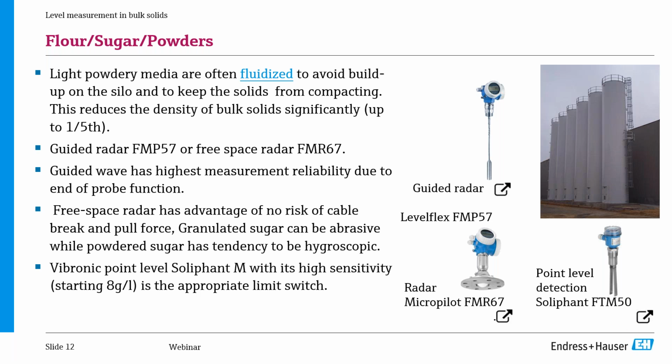Free space radars, depending on the process conditions inside the silo, can suffer what we call echo loss, especially if you have a very dusty cloud inside the silo. Whenever you send a signal, all of this dust will absorb it, and the signal won't be able to return to the instrument. So we have what we call the echo loss. And in these kinds of applications, using a guided radar is really the recommended product to make sure you have a reliable and effective measurement.